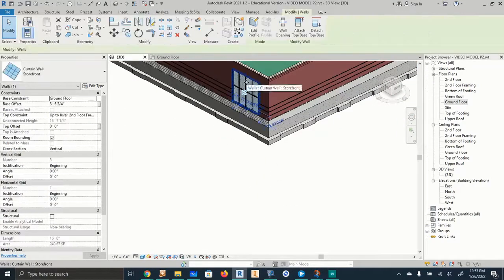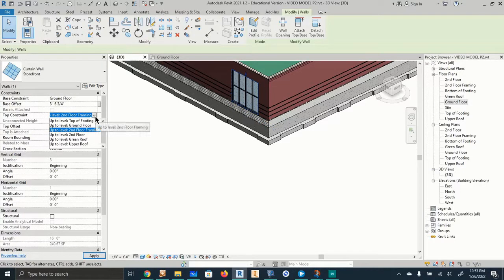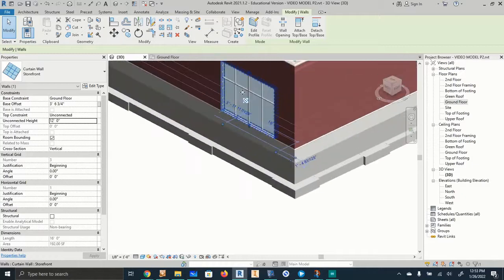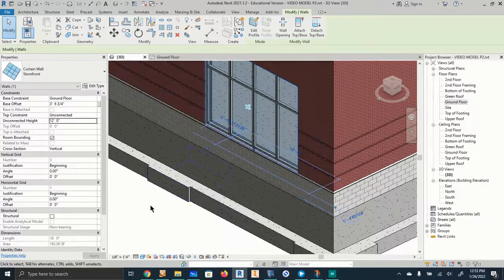Another thing I want to look at, let's check one more thing. Right now it's unconnected. Let's do this. We know we want to be below our framing on the inside, and right now you would see into the top of the area in there that's going to be for equipment. So let's make the top of this 12 feet. And in the upper story, we would make it like 8 feet or so, 8 or 10 feet, okay? So we'll probably do that one separately. But right now, that would work.